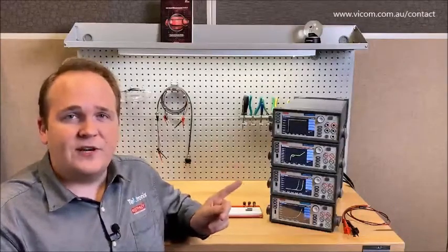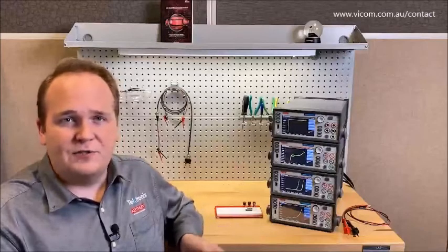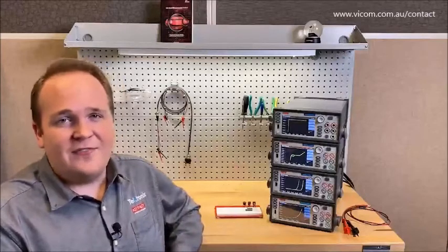I-V Tracer can be used anywhere your SMU can, using either the front or rear terminals, which makes it a very portable solution. Remember that if you want to use voltages above 40 volts, you'll need to use a test fixture that can satisfy interlock. This is to prevent accidentally touching any hazardous voltages. That's particularly relevant for the 2470, which has a 1000 volt range, very helpful for tracing into reverse breakdown voltages. For most cases though, I find a simple breadboard like this one, or even some clip-on leads are sufficient.